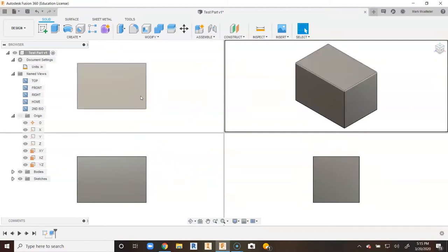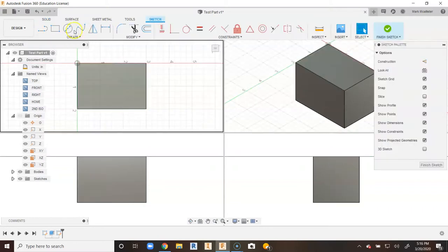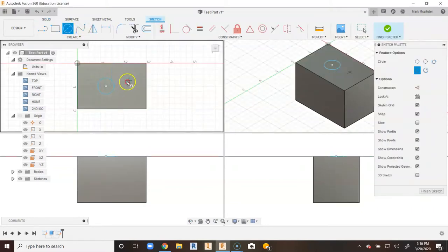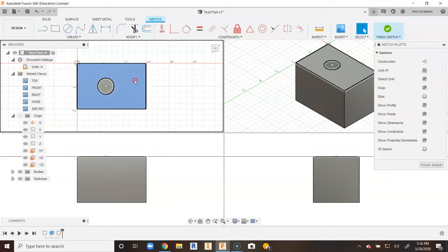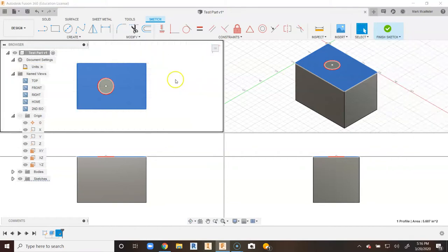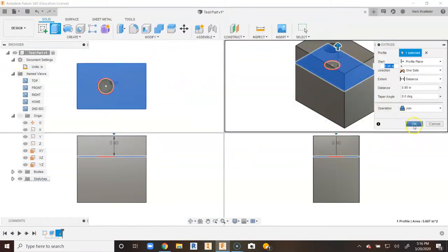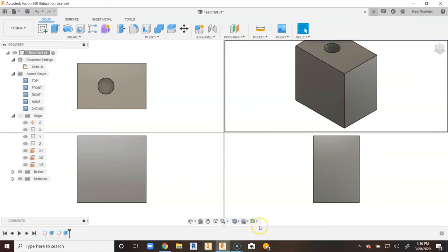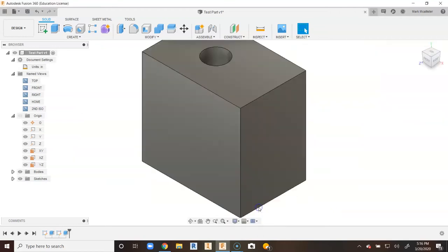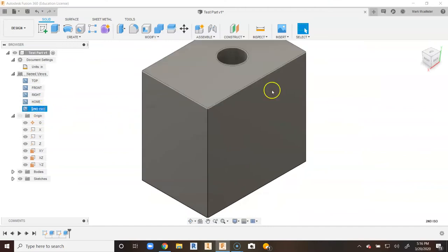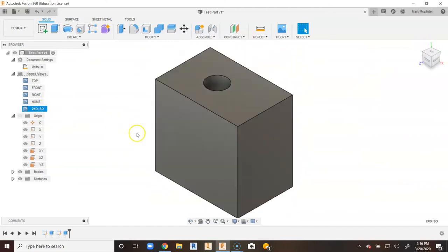So if I change one view on one object, if I go in with the pencil, and on this object right here I draw a circle, and say okay with this, and I'll try to press and pull that area. I'm going to come out to here and go press pull. Even over in this view, I can start dragging up and say okay, and automatically I can see that in 4 different views. Come back to my single view, come back to my second ISO, and I can change my view space however I wish as I go.